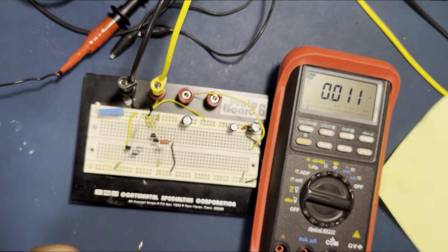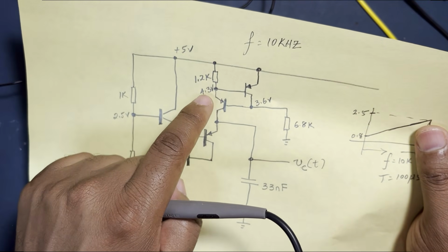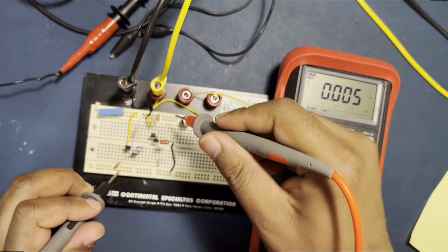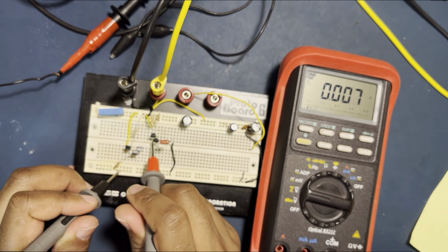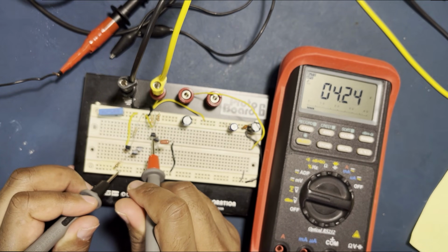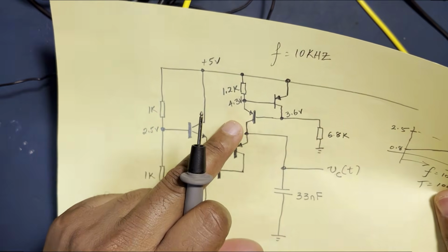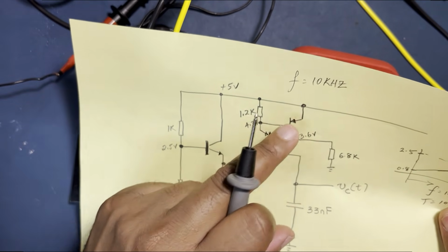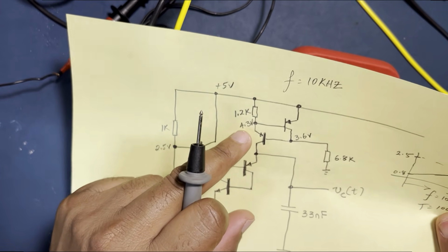Now, what's the other voltage we need to measure? It is this one here, just below there. So we'll go to ground and to the 1.2K resistors. That would be the base of this transistor here. What do we measure? We measure 4.23. We designed for 4.3, but this has slightly less drop. You saw the beta of these transistors is really large. Anyway, we measured 4.23 here instead of 4.3.